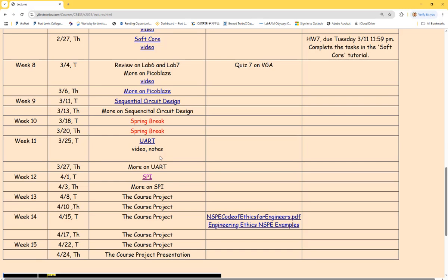Sometimes you get little surges somewhere, and eventually the voltage, which carries the information of the temperature, changes along the transmission line. But digital is fine because digital only reads 0s and 1s. So if there's a little noise in there, it's just changing 0 to 0.1, but it's still read as a 0. So it's more resistant to noise. So in that case, when you are sensing the temperature in the hot tub, you want to digitize your analog temperature data right in the pool. Okay?